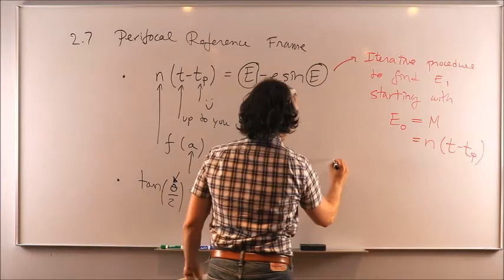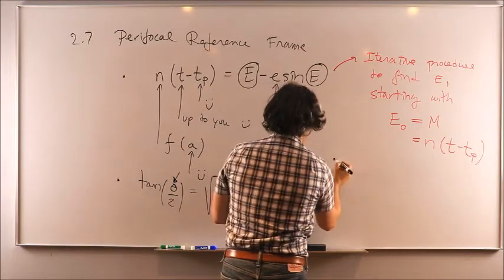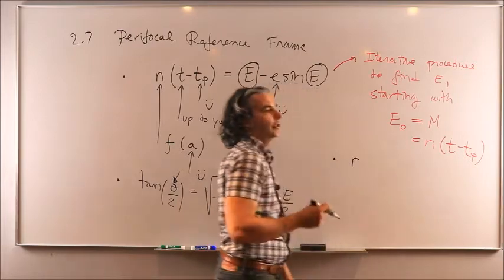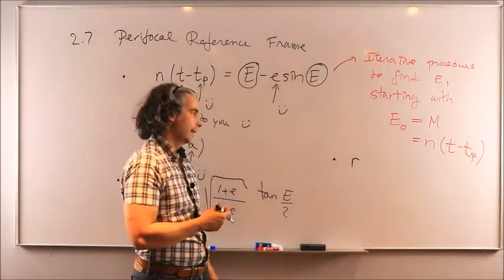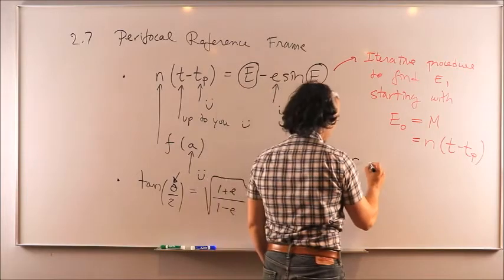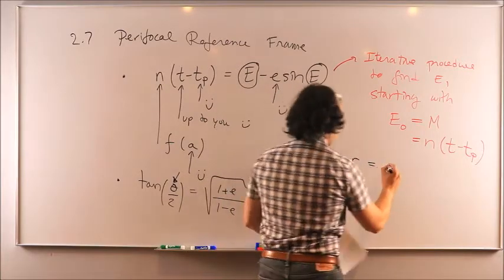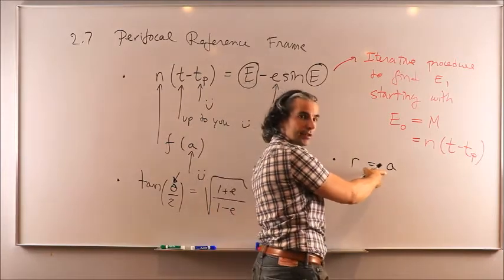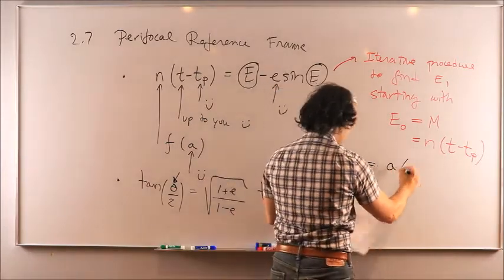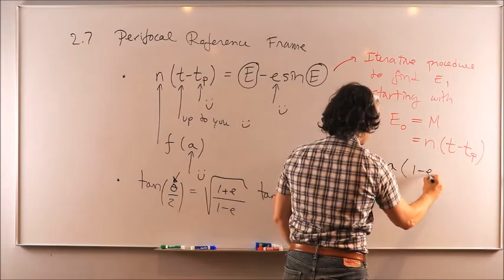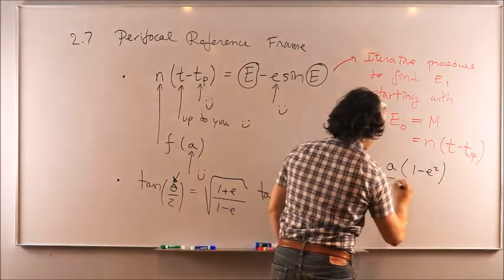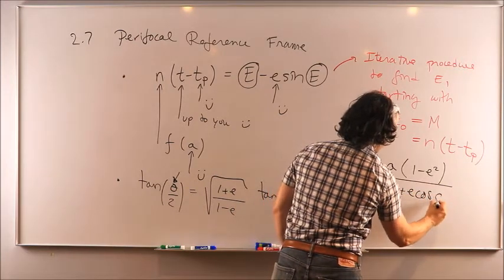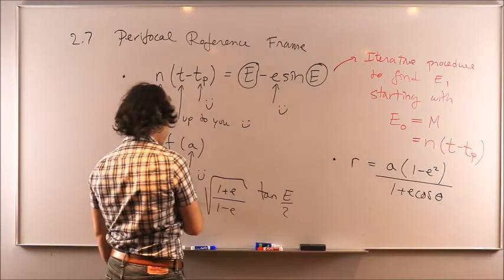That's what you want. Next, once you have the true anomaly, you want to calculate the distance between the spacecraft and the planet using the orbit equation. And we're going to use the version that uses the semi-major axis and the eccentricity for the numerator, because those two things are given to you. Over 1 plus E cos true anomaly that you found in the first step.